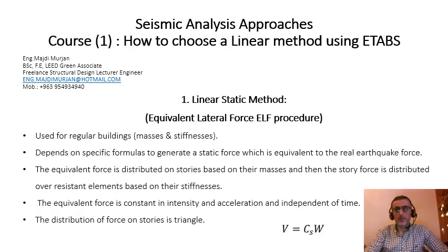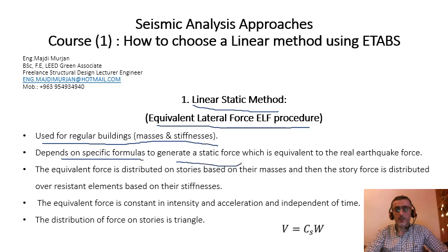Now let's talk about this linear static method, equivalent lateral force procedure. It is used for regular buildings in masses and stiffnesses, and there is a specific formula to generate a static force which is equivalent to the real earthquake force. As you know, this real earthquake force is a dynamic force dependent on time, and it is not static but dynamic.